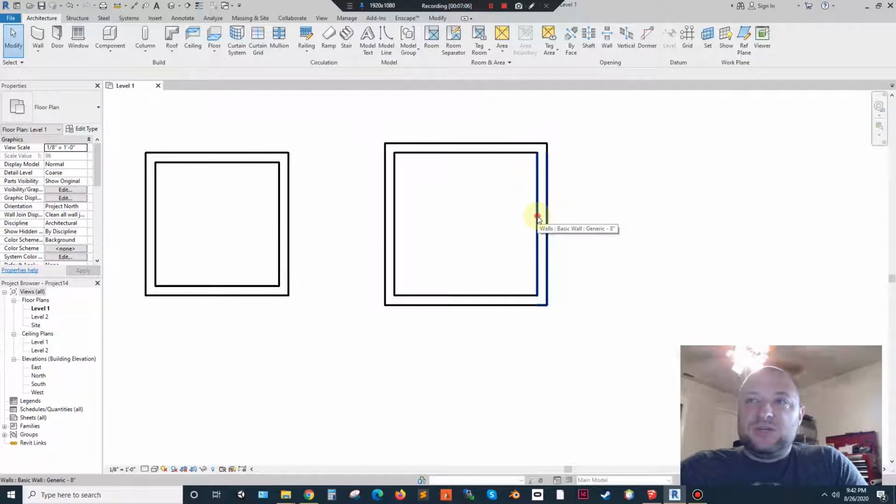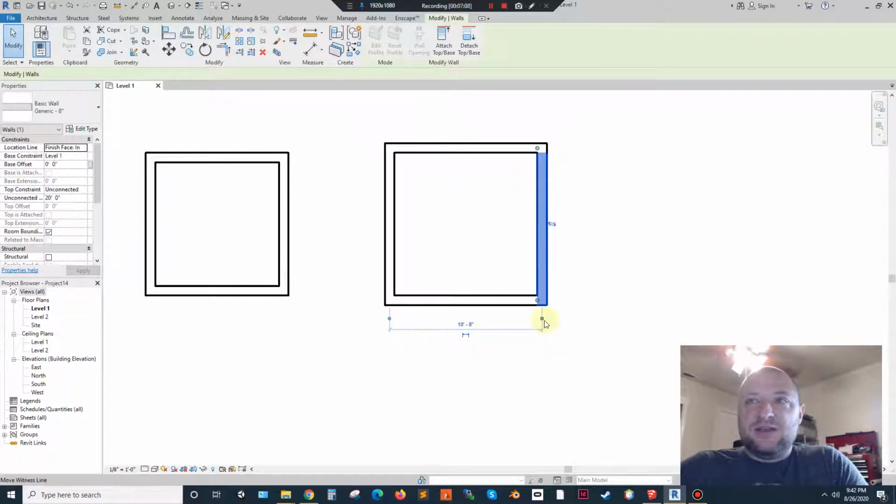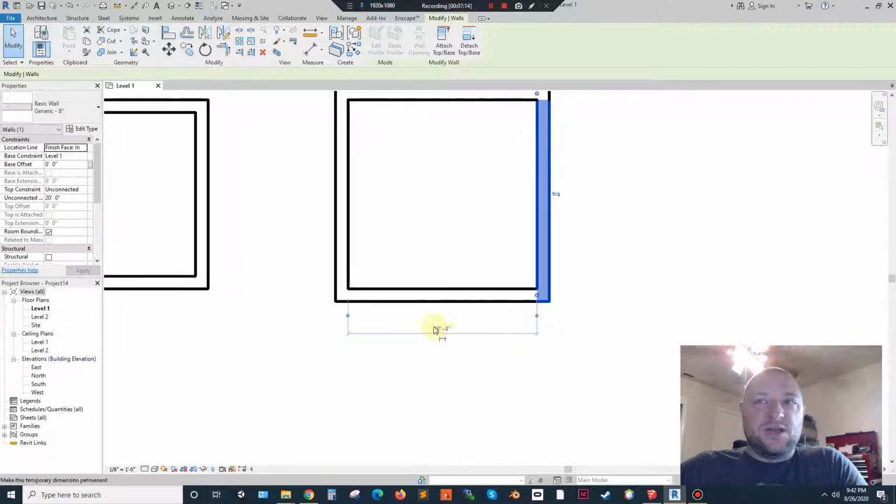Now, if I want to adjust the size of this room, we can see again, I did this one. It should be 10 feet on the inside here. And I can modify which measurement I'm using by clicking these little witness lines right here, and it will cycle between the exterior, center, and interior. So if I just jump around, I can see that right here I'm matching up with that. So that's going to mark my inside dimension for this room.